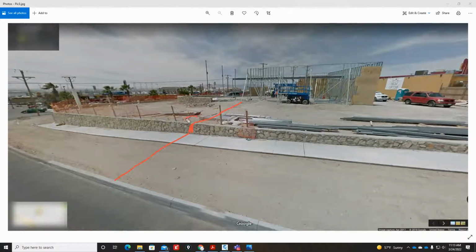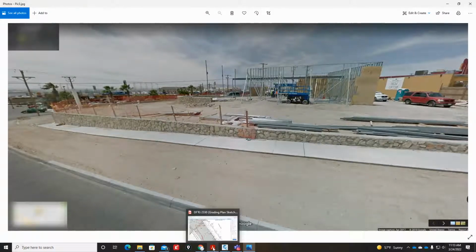To the curb. So this is that little drop that we need to draw, and this is a new wall that's being built, looks like, as part of this construction. So that's a new wall, new sidewalk, and a new curb, but this is existing pavement. So this is what's going to stay. So once again, that's why these section views are so detailed, because there's a lot of information going on here, and you need to understand what's going on, whether by pictures, asking questions, going to the site and seeing it, whatever you need to do, ladies and gentlemen, to get these sections drawn correctly.